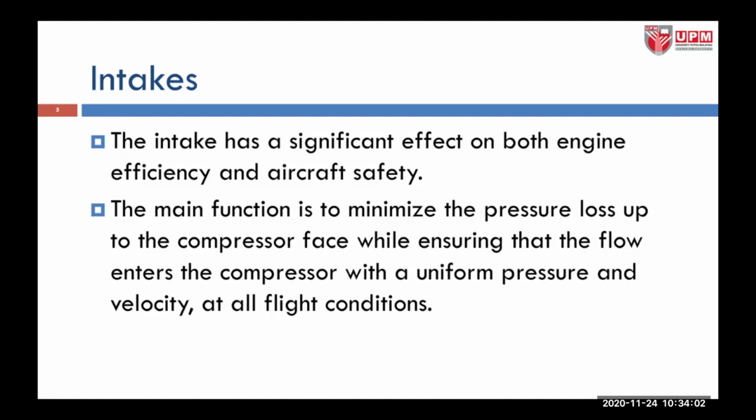Basically, the intake or the inlet prepares the air before it goes to the fan or the compressor phase, while ensuring that the flow enters the compressor with a uniform pressure as well as velocity at all flight conditions. So when you design an inlet or intake, you must ensure the correct angle, the correct length, as well as the area involved, in order to get the correct pressure and velocity and minimize the loss before it goes to the compressor stage.